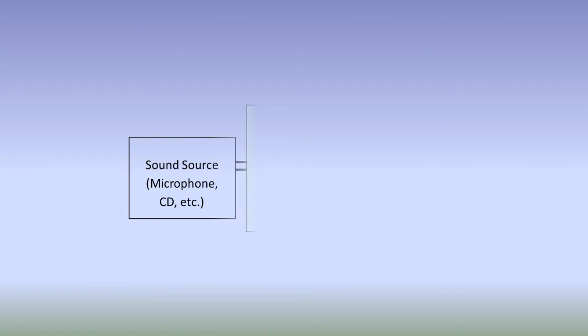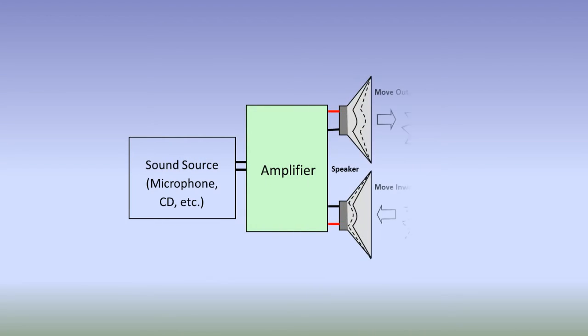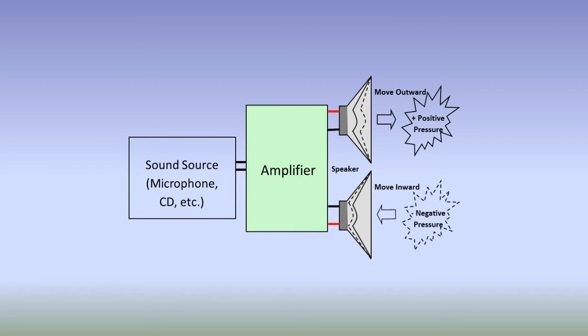The reproduced sound field will be messed up if the speakers are out of phase. For example, if two speakers are emitting the same tone, and one of them is in a state of inverted polarity, those tones, when combined at a given spatial point, will cancel each other. This effect is stronger at lower frequencies and will result in loss of bass and destroy the original stereo imaging.